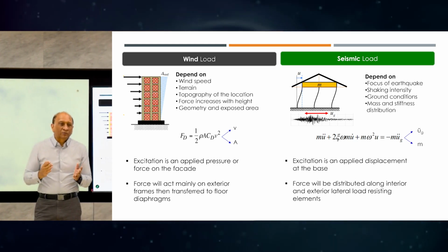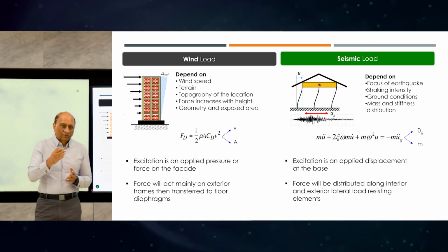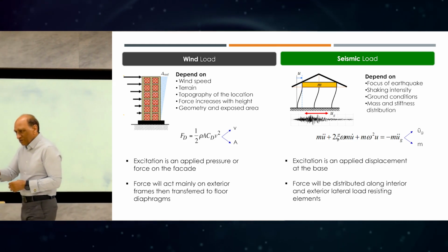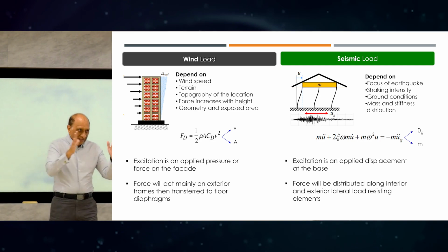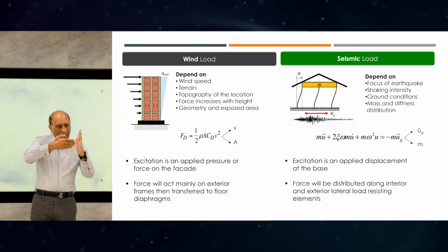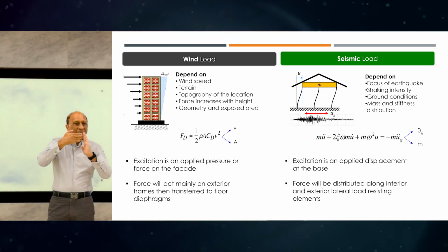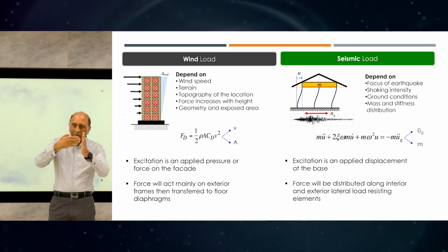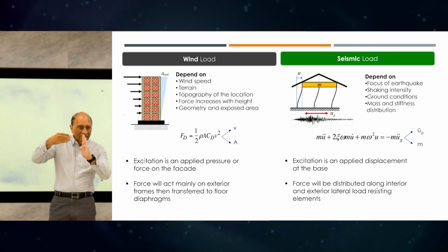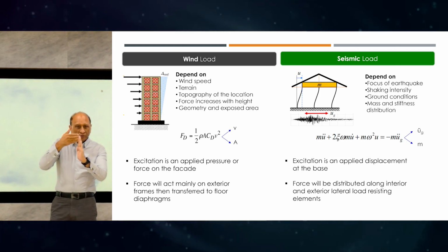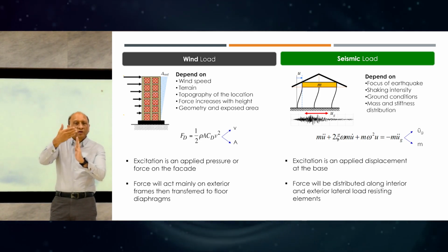So that is even worse than the direct one for many buildings. So we have to consider both the direct pressure from the wind, which is the hitting of the wind from the wind direction, in which the building will deform in the direction of the wind, but at the same time, building will deform perpendicular to the wind. Because when the wind is flowing around the building, it will create vacuum, low pressure zones, and if the building is not symmetrical, they will not be equal.